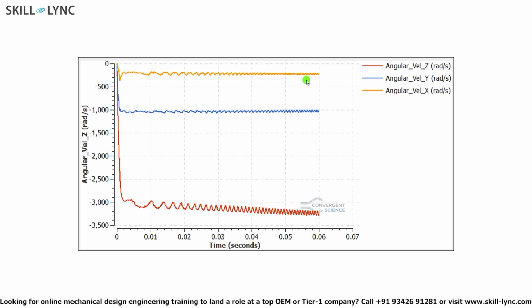Looking at this, one might say that, hey, the simulation has converged and there is no need to run it further. This is one of the classic mistakes that people make, especially in these types of simulations. The reason I'm saying that this is wrong is not because you should not check for convergence in angular velocity values. It's because you should look at other parameters as well.